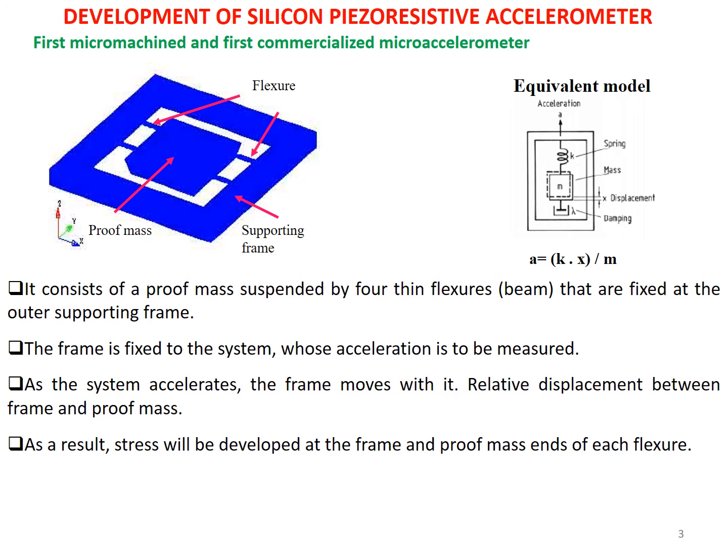Fine. So the simplest piezoresistive accelerometer you can think of is a simple cantilever beam, where on the free side you have the proof mass and the other side will be the anchored region. Fine. And towards the anchored region, or the fixed substrate, we can deposit the piezoresistor, and when that cantilever beam with the mass is subjected to acceleration, it will vibrate, and accordingly the piezoresistance will change, which we can detect with the bridge circuit. Fine. So that is the simplest one.